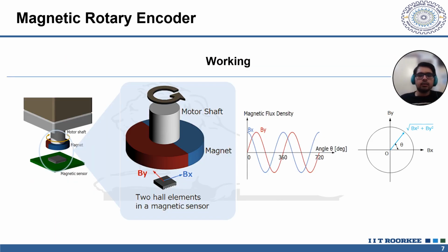A magnetic encoder detects rotational position information as changes of the magnetic field, converts them into electrical signals and outputs them. A magnetic encoder has a shaft end configuration that combines a magnet magnetized in the radial direction. When the motor shaft rotates, the magnetic field created by the permanent magnet attached to the tip of the shaft also rotates. At this time, the magnetic field rotates with constant strength in the area near the center of the rotation axis. The Hall element detects this change of magnetic field distribution and converts it into an electrical signal.